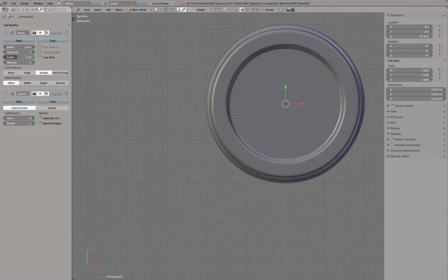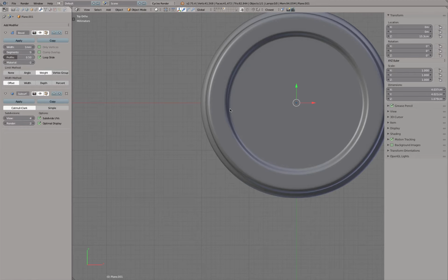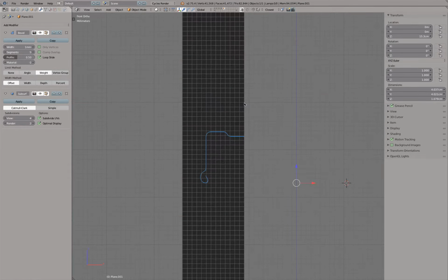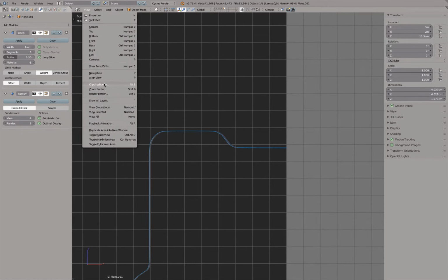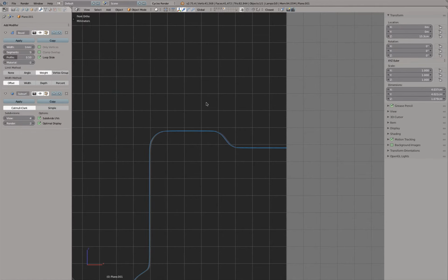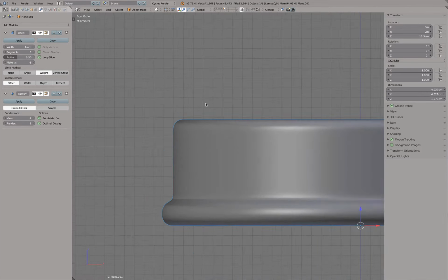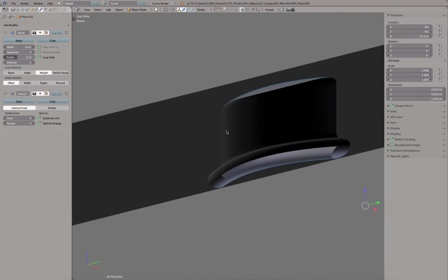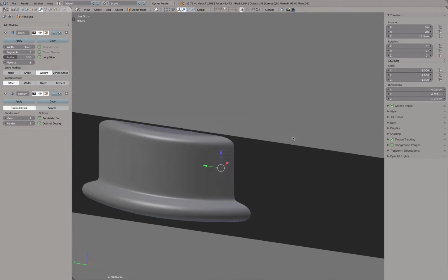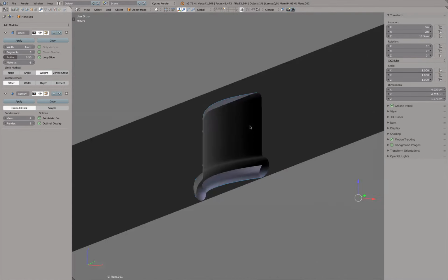Let's maybe make a cross-section view. We can do this by pressing and holding Alt and B and then drawing a selection. And we can actually see how the surface looks. And then to get out of this view, you see this is actually clipping border. We simply press Alt B again. You can also do Alt B from here. And we just see only this part. It's a really nice way when you want to see cut sections.